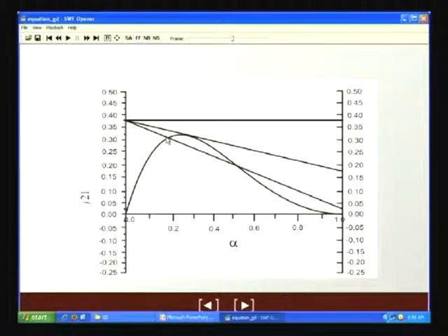What does it denote? Bubbly flow, liquid higher proportion, gas lower proportion, and high alpha, sort of a droplet flow, or maybe annular type where droplets are dispersed in the gas core. Clear? So, therefore, one solution you get at a low alpha, other solution you get at a higher alpha. Clear to all of you?